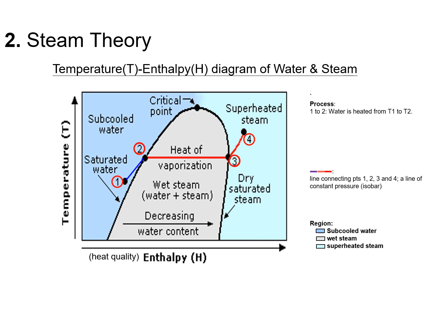From point 1 to point 2, we gradually heat the subcooled water until it starts boiling. Up to point 2, all the heat we add is used to make the water hotter. At this stage, the water is almost turning into steam, and we call it saturated water. This is called sensible heating.